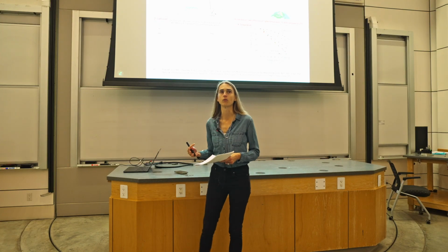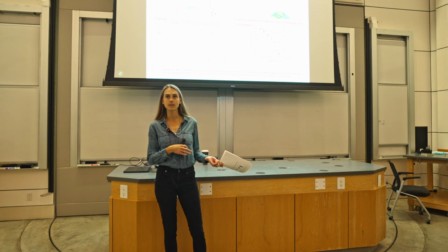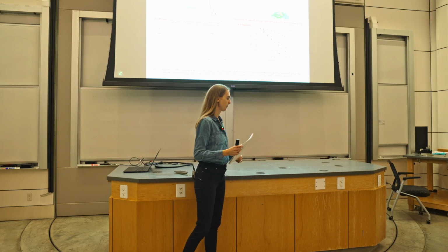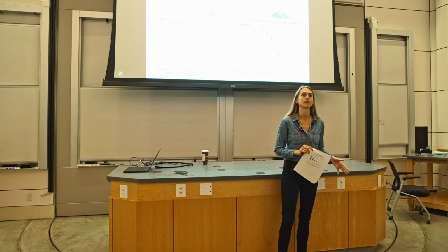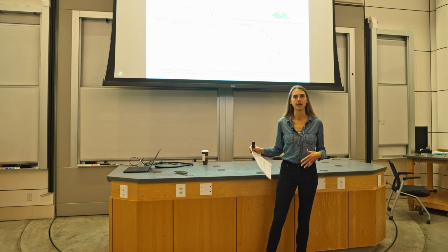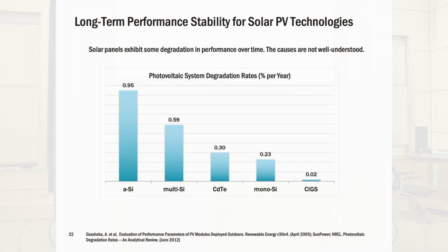And it's something to keep an eye out for because a lot of the industry data out there for solar is in DC, and I've seen journalists and whatnot make mistakes of trying to compare those to AC data from, say, the EIA and make incorrect assumptions and conclusions. Solar PV panels also experience degradation over time, and some more than others. The causes are not all that well understood, but it's something to account for when modeling and designing a solar PV project and its economics and productivity over time.